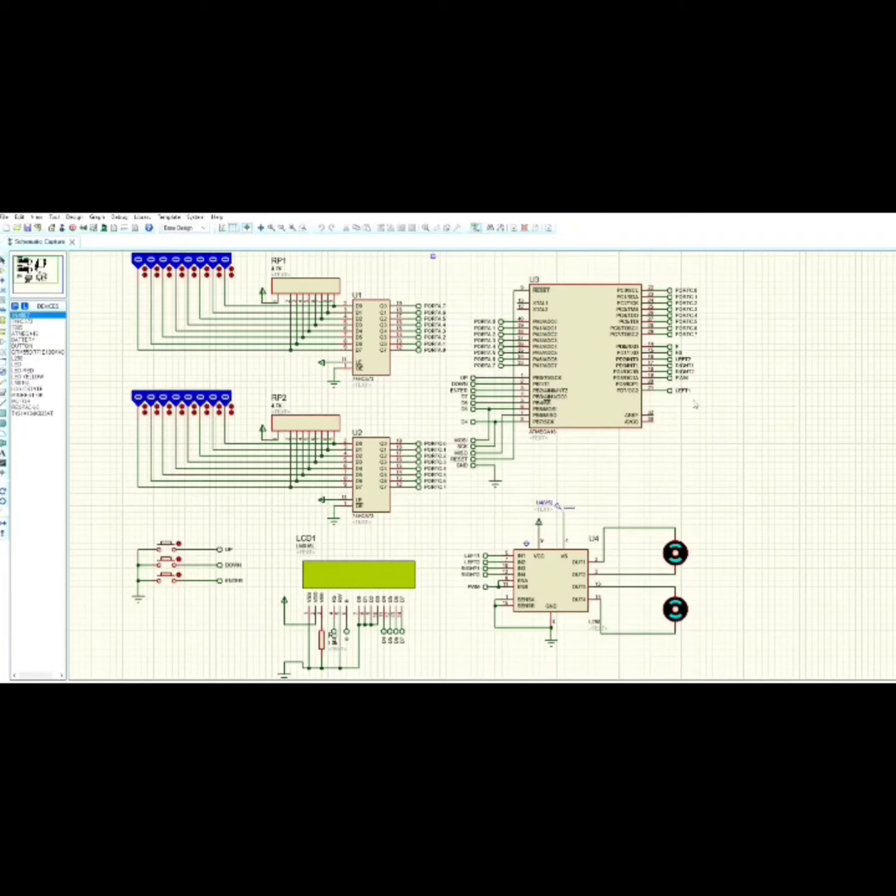I'm here to present our 461 project simulation, which is a line follower. For this line follower, we have used, first of all, 16 logic states as 16 light sensors. As these light sensors need a lot of current supply, we have used 2 buffer ICs, one for each 8 of them, and each buffer IC has its own power supply at pin number 11, which is here.